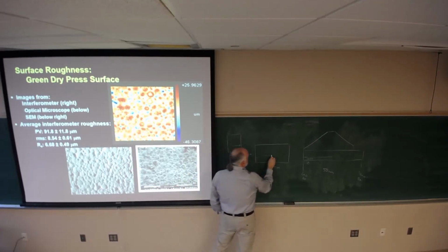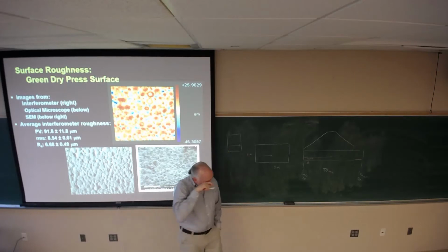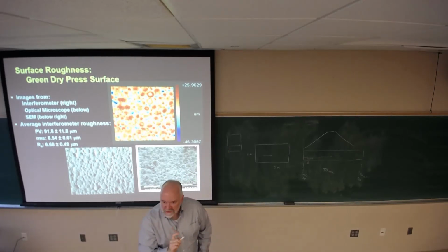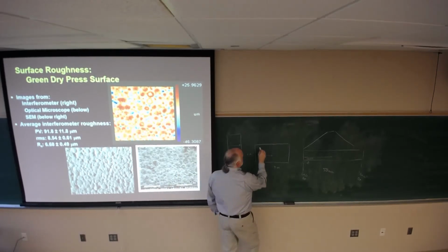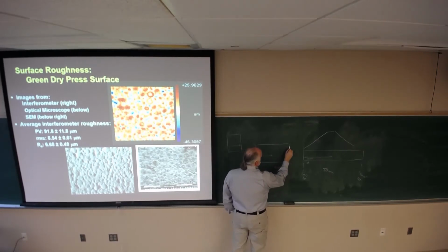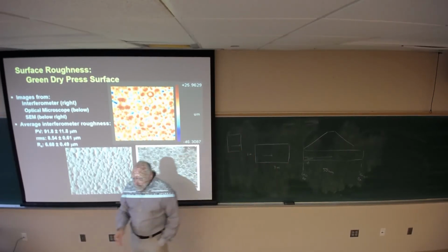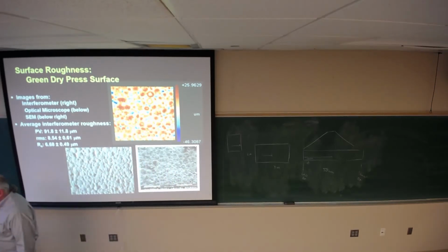Moving through the kiln, this surface, the front leading edge, will be hot before the back edge is, and in fact, it will sinter first. So you can look in the kiln and see that it's sintering as it goes through, and it is shrinking non-uniformly as it goes through that. It comes out fine.